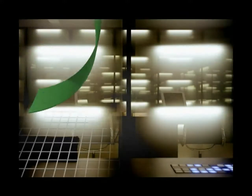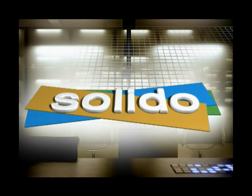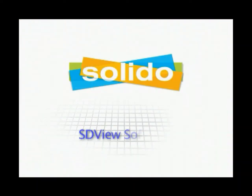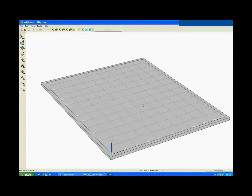The SDView Application software is the bridge between your CAD system and the SD300 printer. The SDView software will help you prepare models for the build. To open the SDView software application, please double-click on the icon. When opening the SDView Application software, the virtual work table will appear.